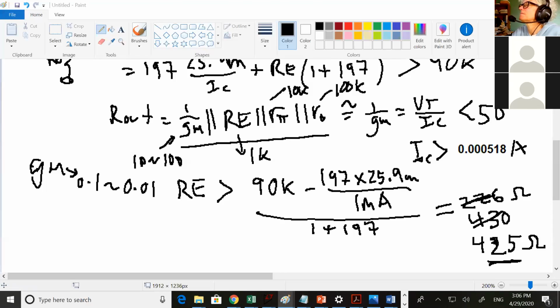So, Professor, the reason why you were able to turn the dependent current source into a resistor was because, again, with the R out case, you're grounding V in. That base voltage is now 0. The emitter voltage is still the emitter voltage.